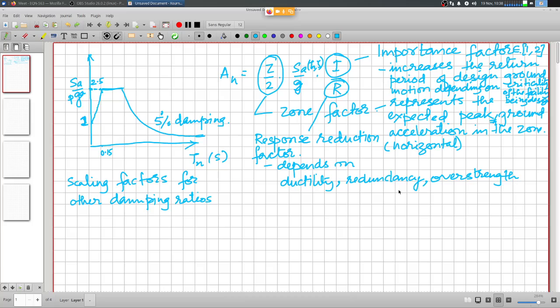If you look at the definition of the yield strength of reinforcing bar in the code, you will find that the terminology is not that the bar yields at this particular stress. It only says the bar should not yield at a stress level lower than this. So what is the higher yield level, it is not specified.